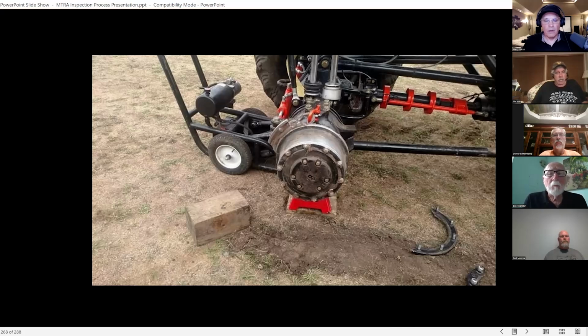Super critical. Guys tire up and get talking or something and don't finish putting the wheel on, or maybe they only put 5 on to tighten it because they used the 5 that were on the transport tire, and then they have to go get the lug nut box and bring the lug nuts over and put the rest of them on. Well, they forgot to do that. They had a sandwich or something and sat down and didn't put the rest on. If you're an inspector, it doesn't hurt to poke your head in the wheel and make sure they're all in there.